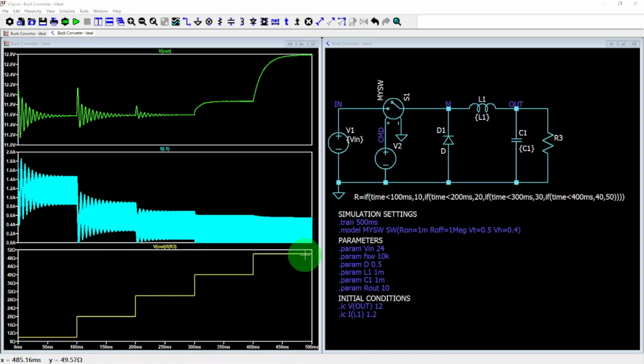As we reduce the load, the converter initially behaves as expected. We do observe an overvoltage, but we understand its origin. What's concerning is that as the load resistance reaches 40 ohms and higher, the output voltage seems to drift out of control. Something unusual must be occurring.